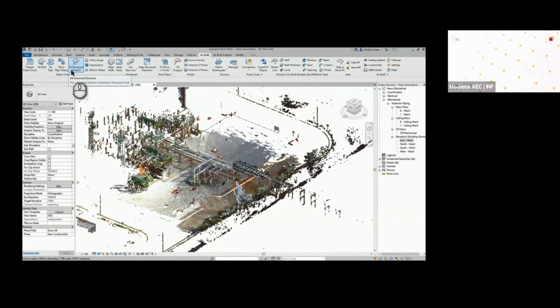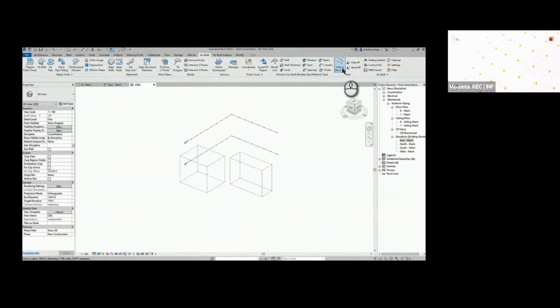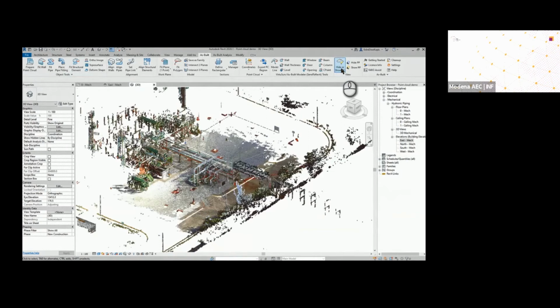So the idea, instead of navigating long queues for templates and visual graphics boxes to switch off your point cloud, you can simply go to the hide or show point cloud function. Select to switch off, and again, select to switch on. This is a simple, small feature that comes with the AsBuilt package that helps you leverage your modeling skills even further with less time waste and delays.